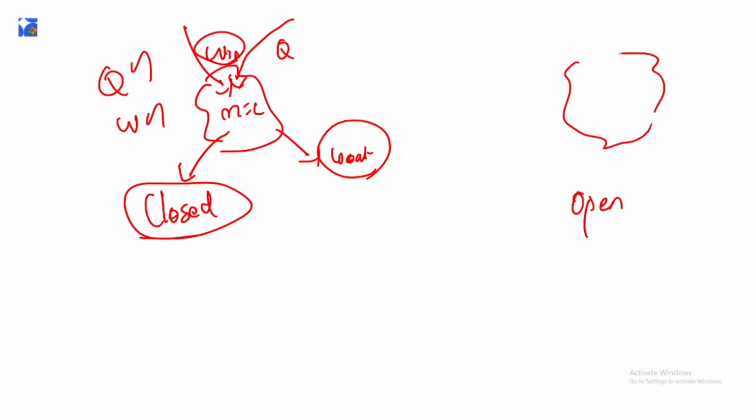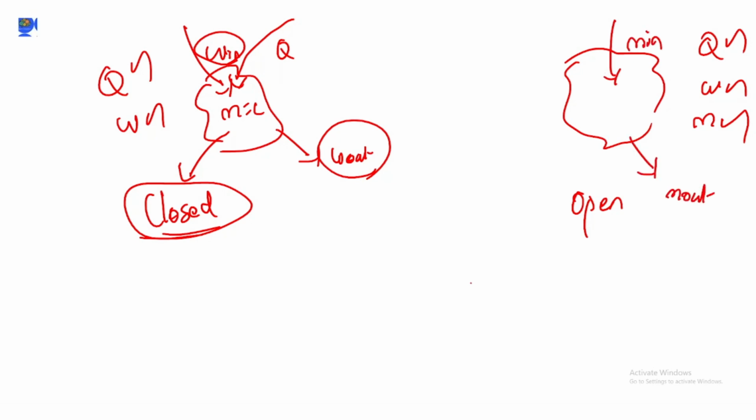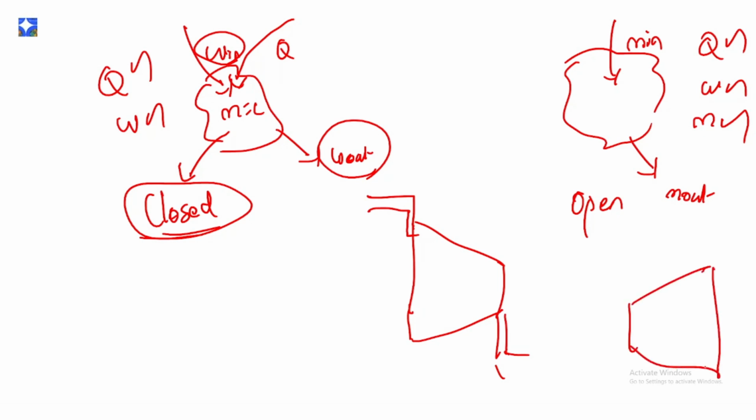So an open system is one where, in addition to heat interaction and work interaction, as we have seen in closed system, mass interaction will also be there. There will be some mass in and there will be some mass out. So there are many such open devices, for example, compressors. In air compressors, air with some mass flow rate enters and then goes out. Similarly, you have turbines, either steam turbine or hydraulic turbine. You have certain mass of steam entering in and certain mass of steam leaving out. In addition to heat interaction and work interaction, mass interaction also takes place.